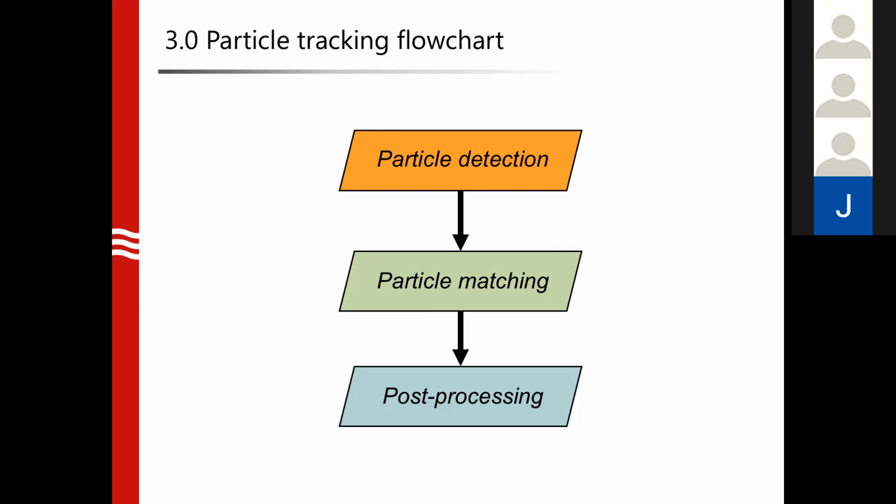The movement of the centroid of each particle is the displacement. After solving the particle matching or linking, you can further use the displacement field to compute many things like velocity and strain fields. So there are other post-processing steps there. The most difficult and important ones are particle detection and particle matching or linking. After finishing these 2 parts, all the other stuff is quite straightforward.